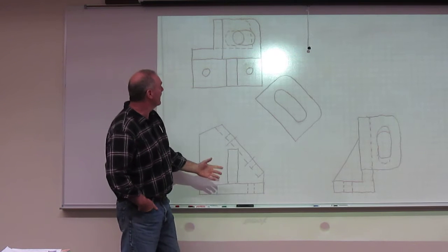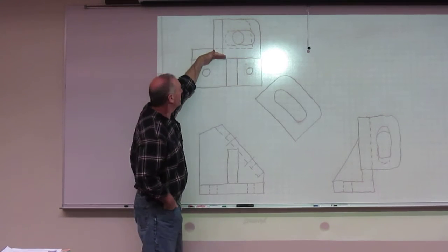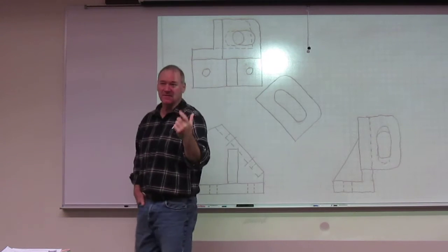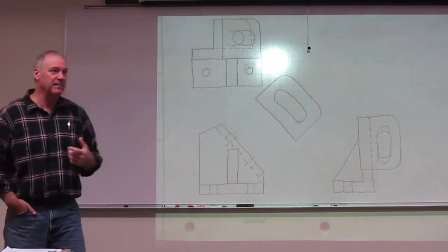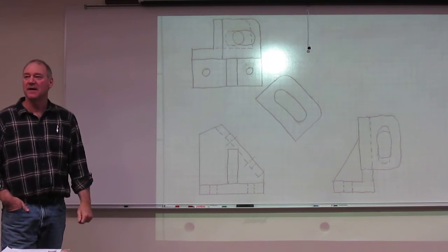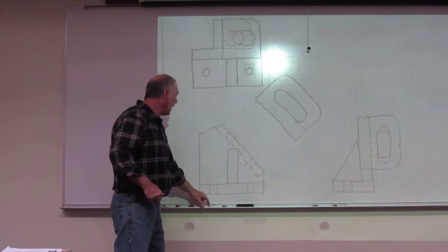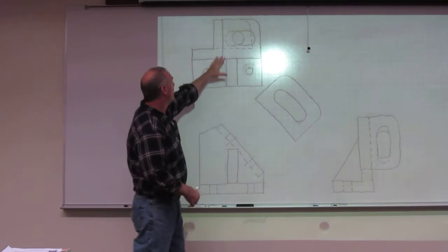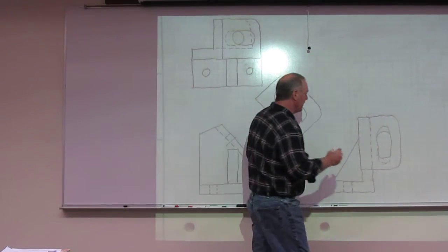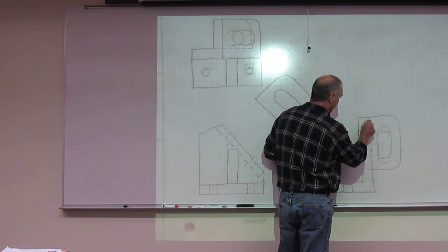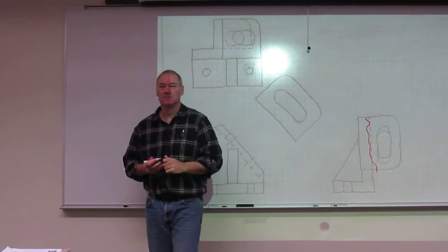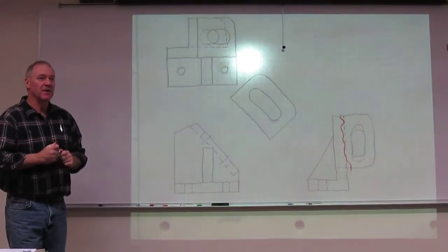So in essence, I kind of look at it as from here back and here back. Those are both foreshortened views. Certainly we need to tie one of them together so we show how it's done, but neither one of those has really given us anything other than how the things are tied together. So in my mind, I would probably be looking at drawing this one in its entirety or this one in its entirety, either or, and then I would do a partial on the other one. So I'd maybe come in here and do something like that and do a partial view, just so I don't confuse the issue.